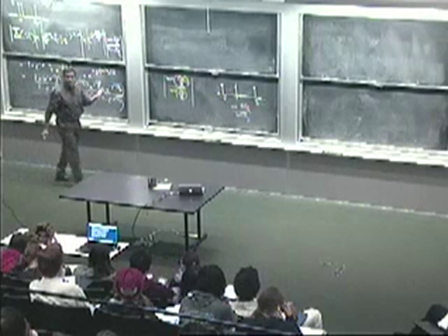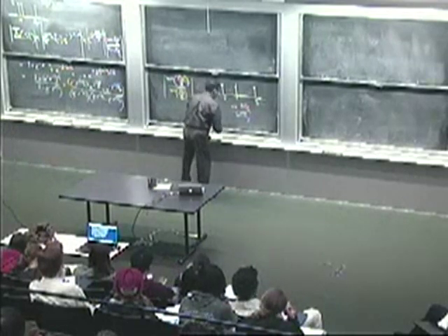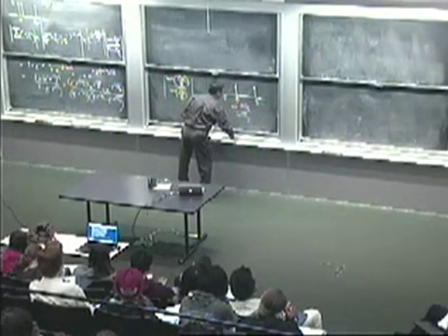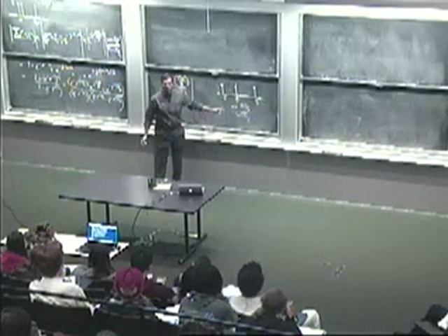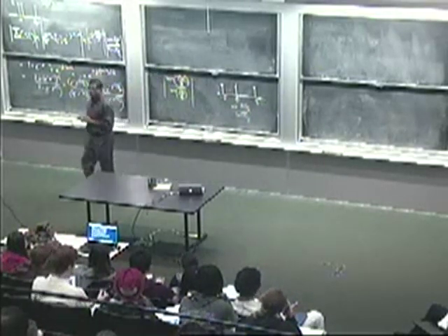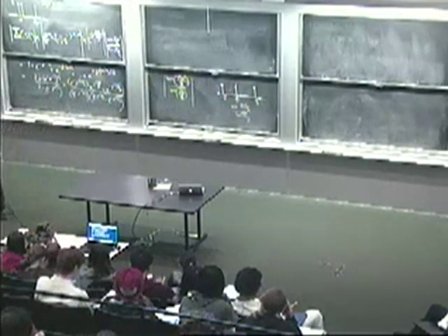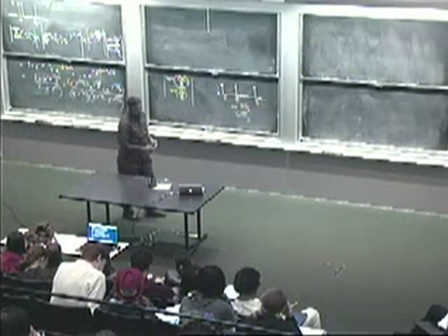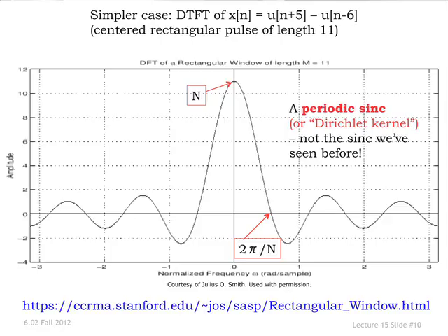So in the case of a symmetrical pulse, symmetrical about the origin, that phase factor goes away, and the actual transform is just that piece without the e to the anything. Sorry, I jumped over a few steps in describing that. Just to go back a second, this is not a sinc function, but it's actually referred to as a periodic sinc. It's got a fancier name also. It crops up all over the place.